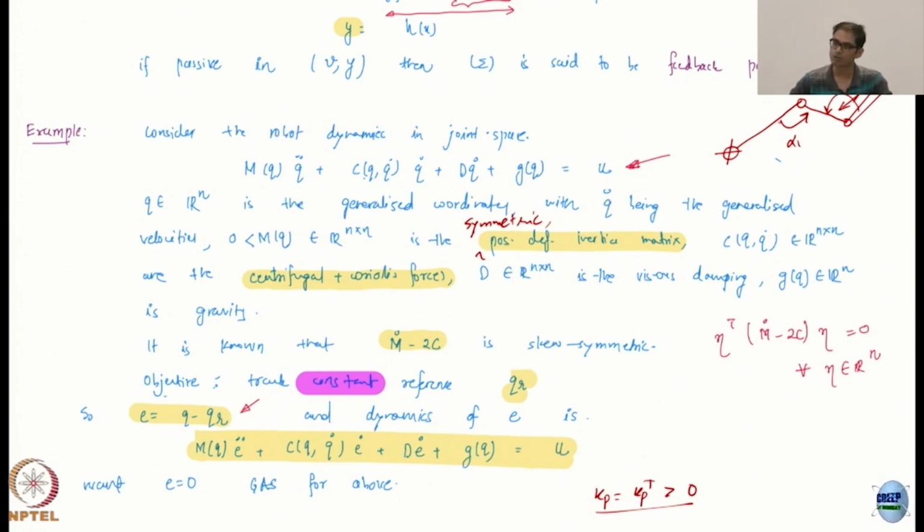In fact, even mobile robots can be modeled in this if it's an omnidirectional robot. If you have an omnidirectional mobile robot, that can also be modeled like this, no problem. So that's the nice thing. This encapsulates a lot of different systems. The control is on the right hand side. Typically, you will see the control as being motors mounted on the joints for angular motion. For linear motion also you can have linear actuators. So that is the control, typically like a torque or a force.